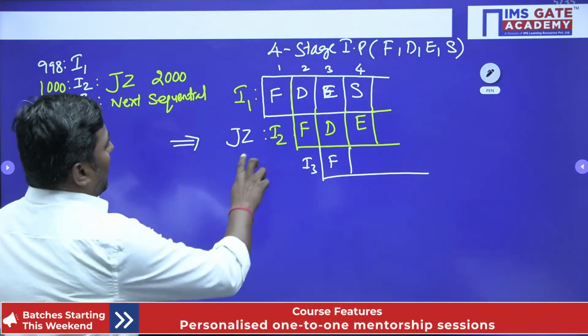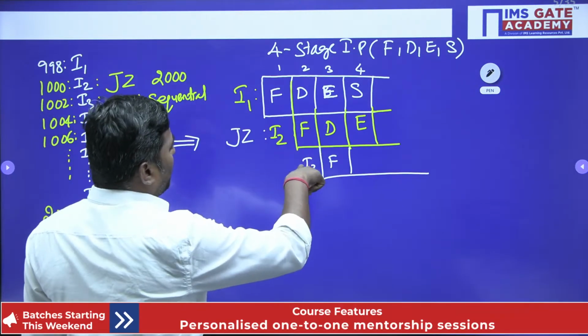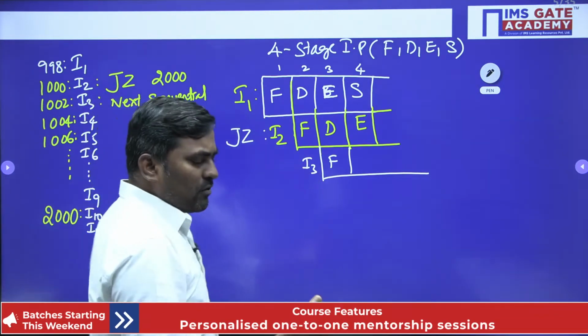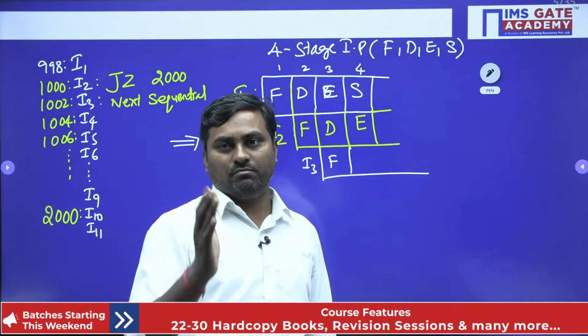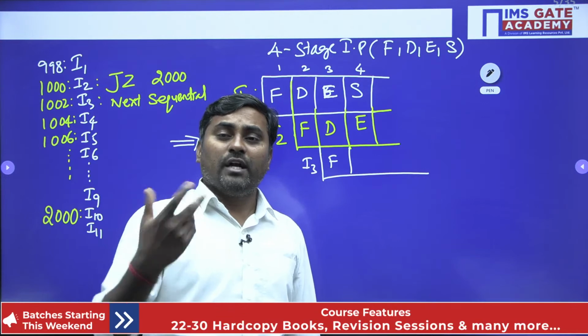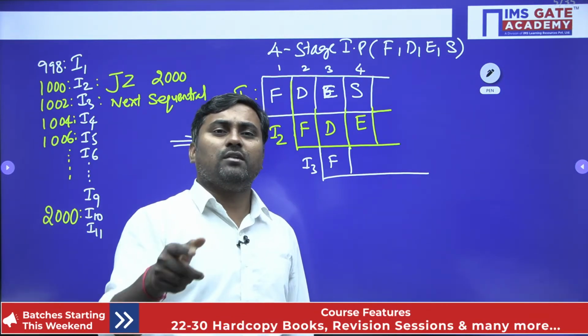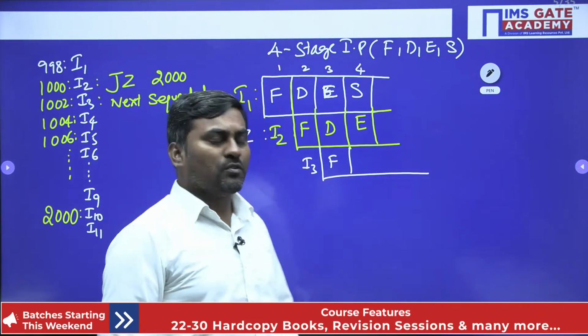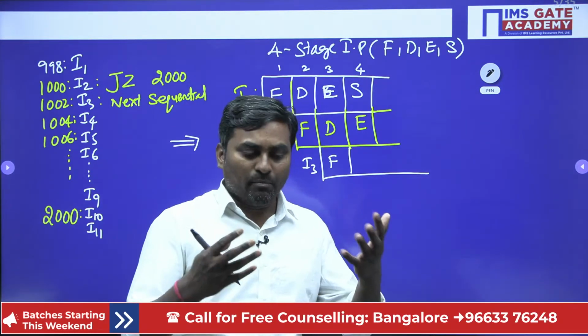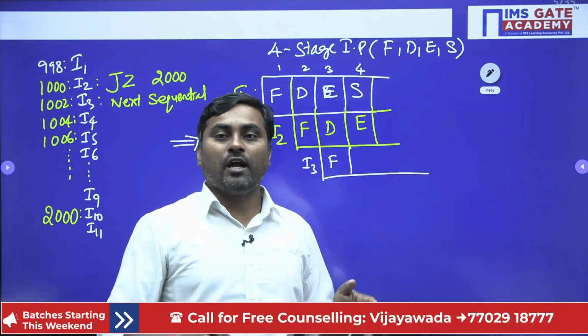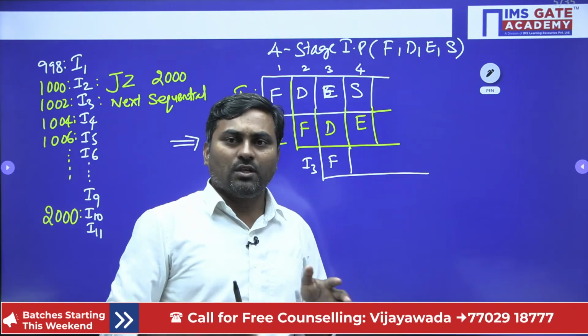Now look, I2 instruction fetch is over, PC is pointed to I3. We don't know whether the branch is going to be true or not, but I3 got fetched. Reason: at the end of the fetch stage, PC gets incremented, pointing to I3. So when will the branch give the result, whether to go to the target instruction or the sequential instruction?